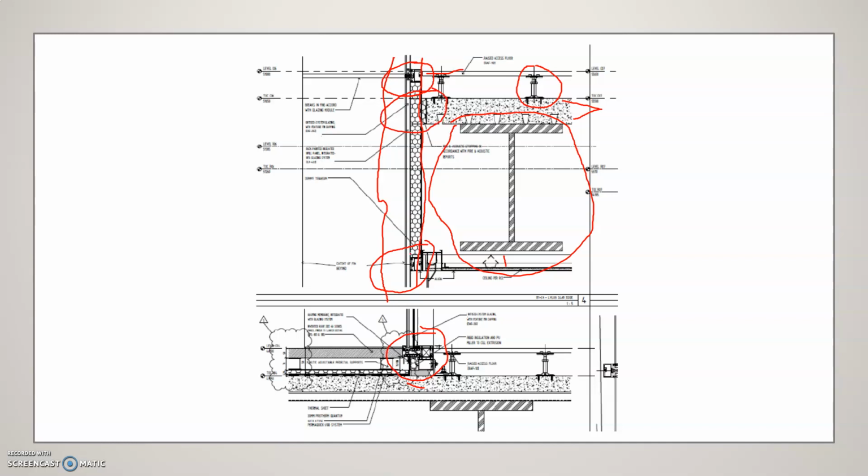Looking at this curtain walling element, we go double glazing unit, so that's one layer of glass, and then this is another layer of glass. Behind this glass we've got some sort of insulated panel with a backing tray, which means the architect is trying not to show the inside, because we don't want to see the ceiling.